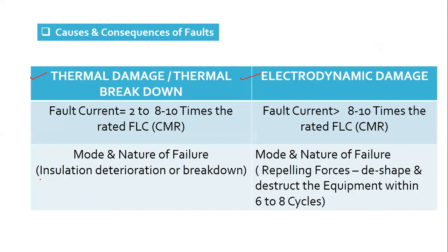Thermal damage is the deterioration or breakdown of insulation, whereas electrodynamic damage is because of the repelling forces generated due to high fault current, and it can result in structural damage, which is the more severe type of damage in the equipment.